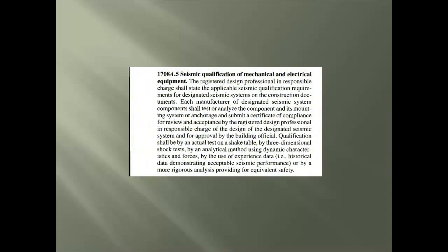Here's an important piece of code for the mechanical and electrical QC professionals. When a piece of equipment is to be subjected to seismic forces before it can be installed, each manufacturer must have the test results analyzed and accepted by the design professional and approved by the building official. What is the actual test required? A shaker table test.